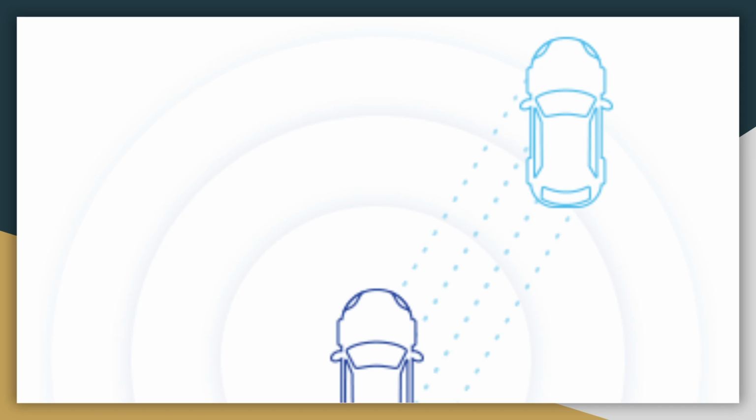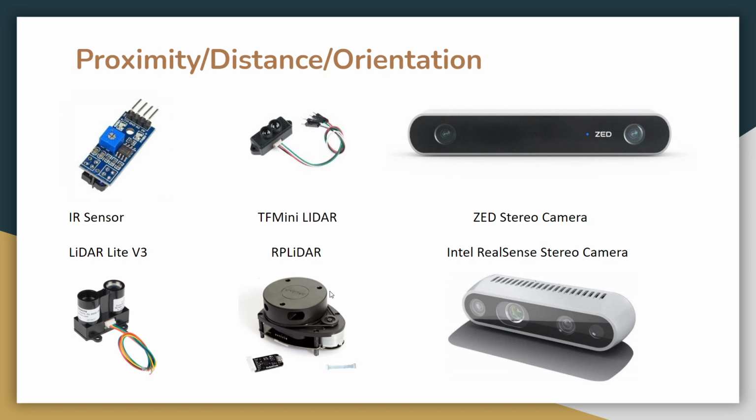The whole sensing is done on a two-dimensional plane which is parallel to the ground. This 2D plane is elevated a bit from the ground, and it's just kept over there where the lidar is. So that whole sensing is done exactly on one plane, and anything below that plane or above that plane isn't really sensed. So that's one of the main disadvantages of the RP lidar.